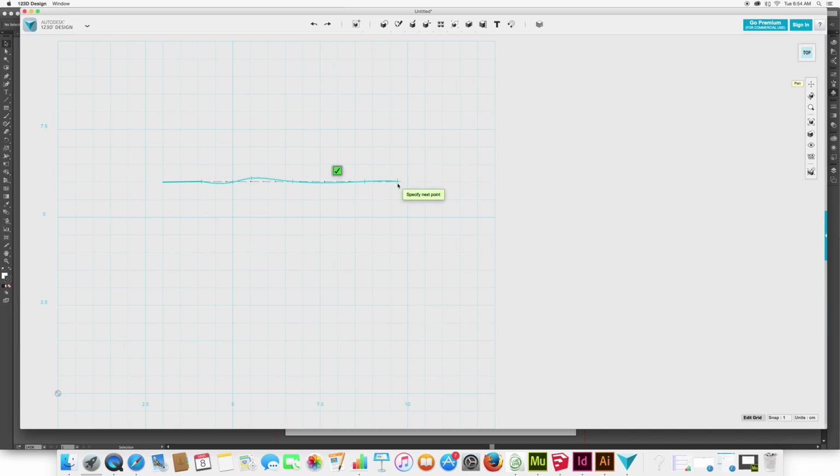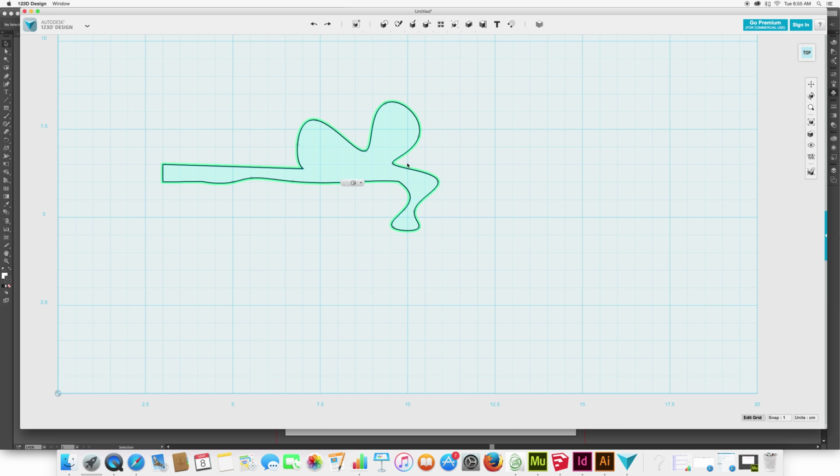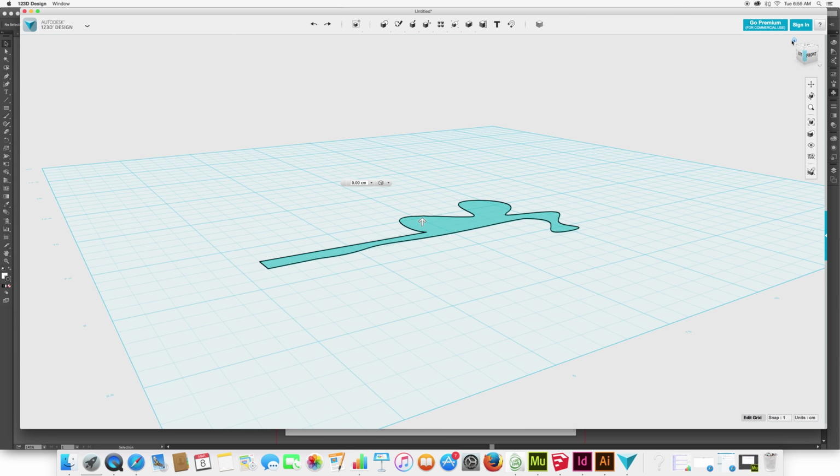So again, decide where you work best and which program. Once you've created that protruding structure, I'm just going to create something rough right now so that we have something to base off of. Okay, this is my beautiful branch, let's say, that we're creating. But once you have that closed shape, you'll actually get a fill. And then with this fill, you'll be able to take your extrude tool, go to the side view, and extrude it to the measurement you wanted.